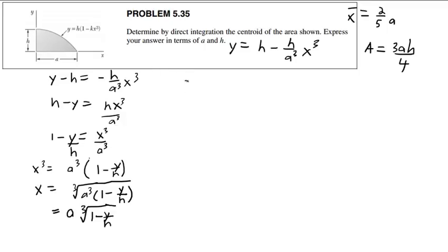Because here's the issue, I'm looking ahead, and my dA is going to be horizontal, like this. Why should you pick horizontal rather than vertical? Because there's going to be a y component in there, right? The qx, remember? qx is the integral of y dA. And this y is what's going to give us trouble in the integral. That's the issue I'm seeing. It won't just drop off, no.